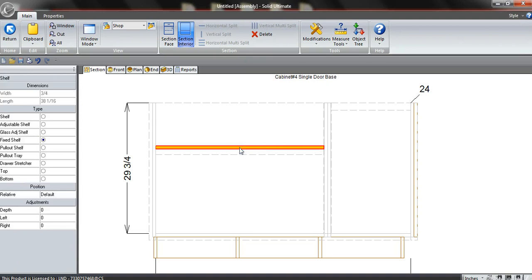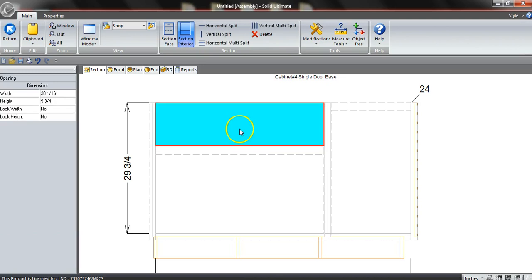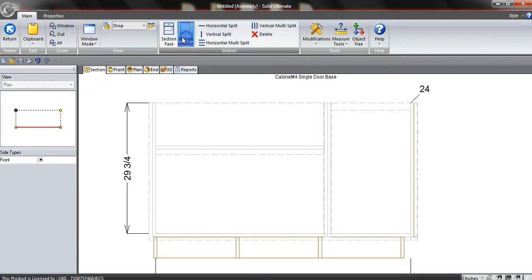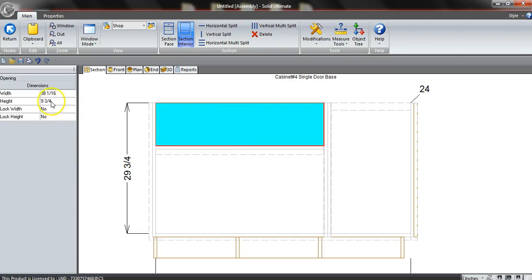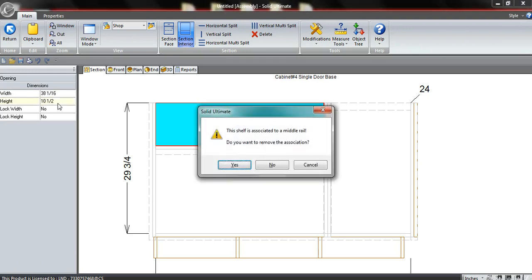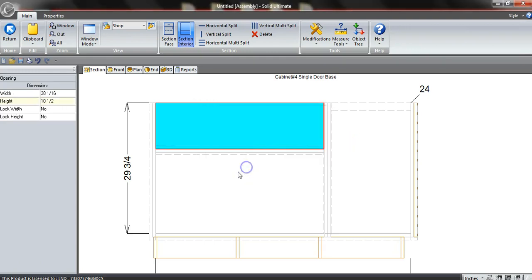This guy here, now what's cool is I like to keep these about a 1/4 inch down from the lip on a farmhouse, right? Or even set 3/4 sometimes, depending on the layout, right? So I'll take this right here. So this isn't representative because it's in the interior. This is your box parts. Just think frame parts, box parts. So what I can do now is take that and add 3/4 to it, right? So we're going to go 10.5. And then boom.